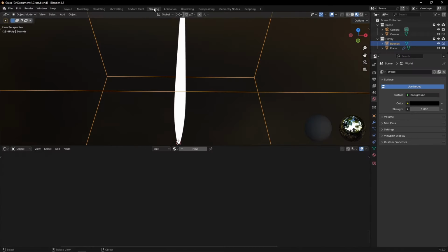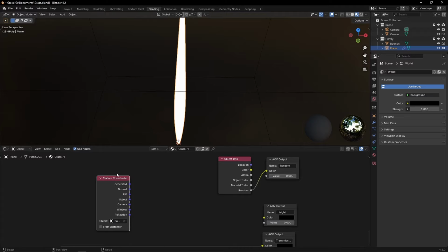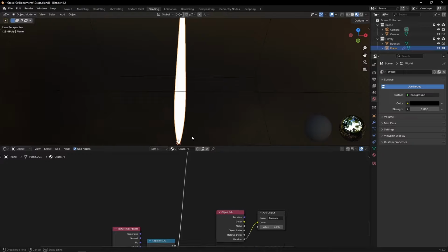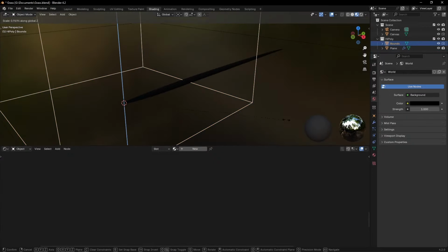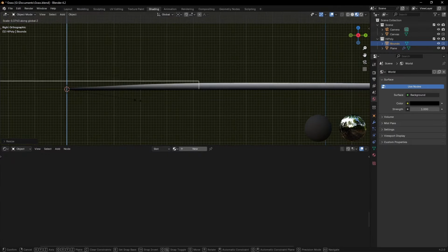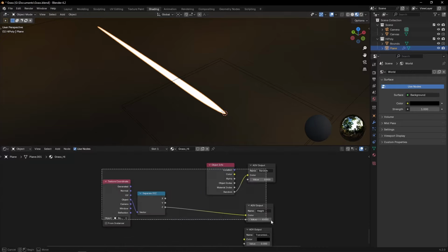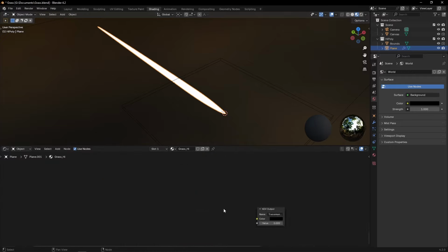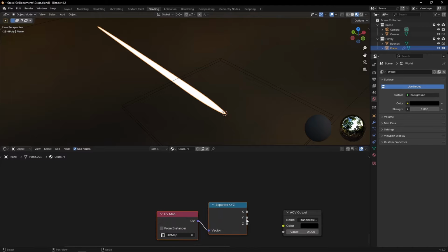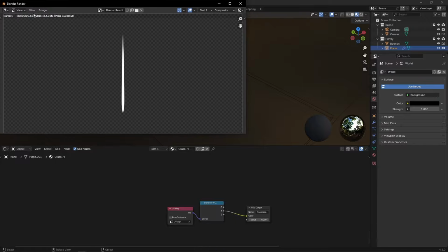Next, using a texture coordinate node, I can specify this cube to generate object coordinates, isolate the Z component to create a vertical gradient, and therefore generate a height map. Just have to scale the cube in Z and shift its Z position to create the desired range. Finally, for the transmission, I may simply use a top-down gradient derived from UVs as well. Voila, at that point I just have to do a render to save all PBR passes to disk.